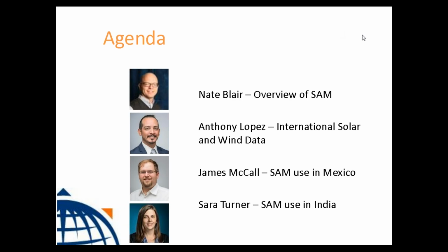There's a question here about soiling losses, and SAM does consider soiling losses. I think one of the things that's interesting is that the data coming out of India, which Sarah was talking about, shows soiling can be quite a bit higher for some of the existing systems, at least in India, than we typically assume in the US. Depending on where you're located, what kind of environment you have, how much it rains, et cetera, soiling can be a really significant issue. And for CSP systems, that's aggravated even more because of the concentrated nature of the technology.